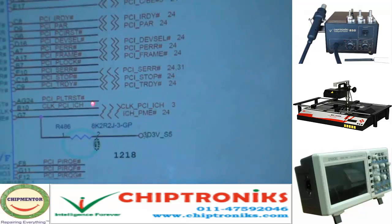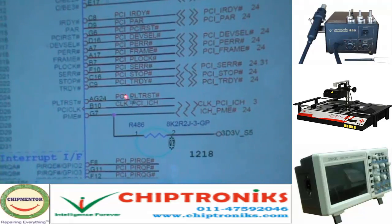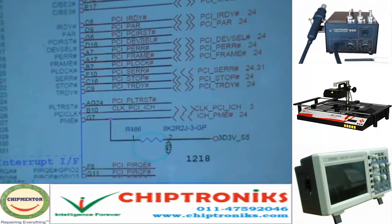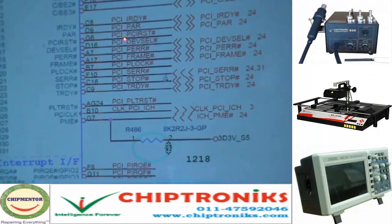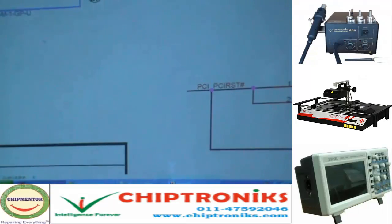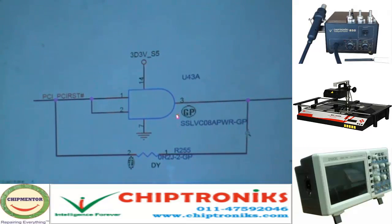PCI_PLT_RESET: the pin name is PLT reset, but the signal is PCI_PLT_RESET. The second signal is this one, PCI_PCI_RESET. Just below this diagram you will see this is the U43A IC. This signal is fed to the U43A IC.